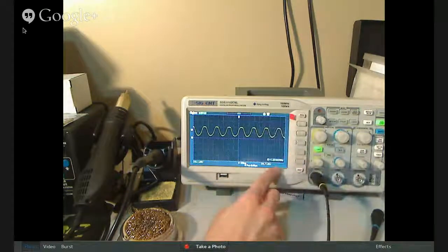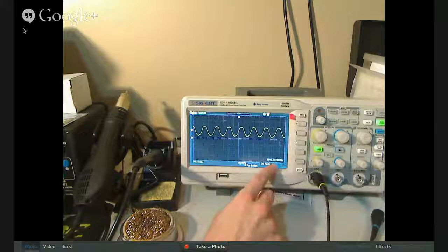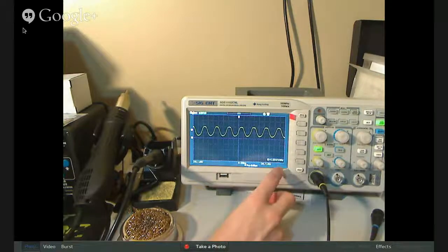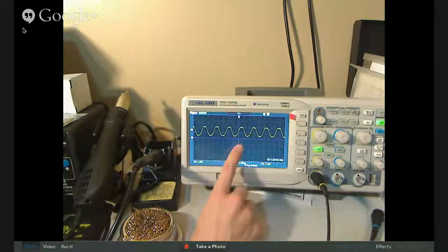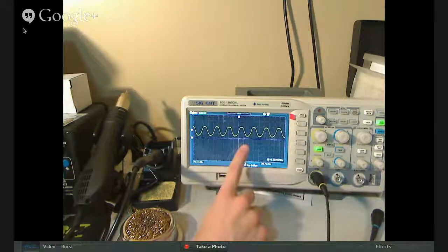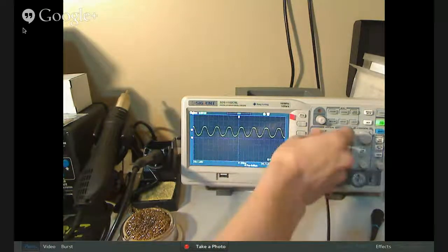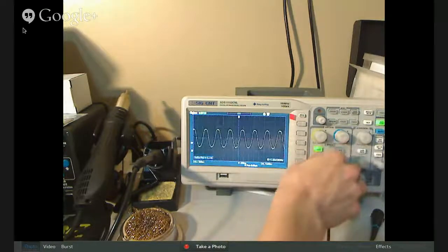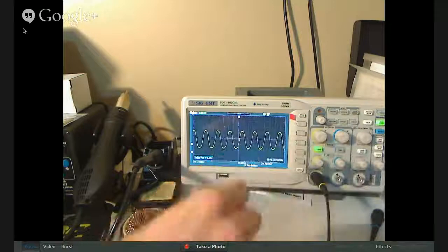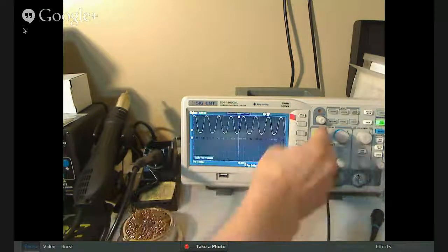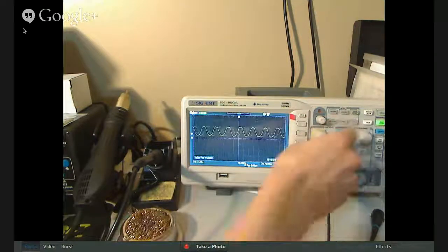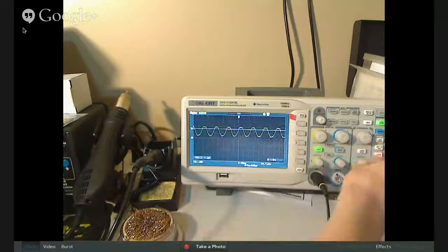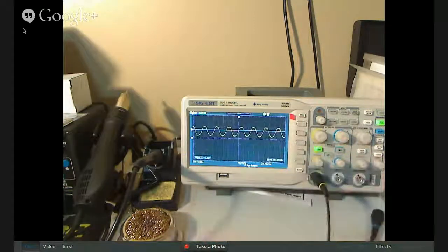We actually do have a frequency counter running down there. It's hard to see, but this is running at about 1.65 megahertz. So basically what we've got here is an oscillator. It looks a bit like a sine wave. It's a little deformed. If we make it bigger, yeah, it's got some phase variance in it. Let's put that back and trigger so that we're sane still.